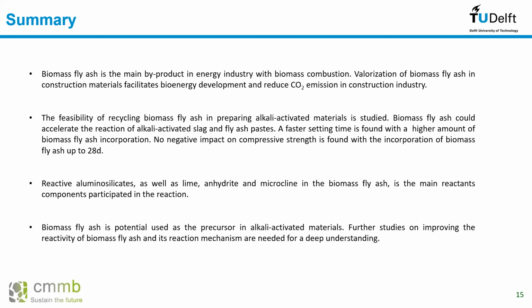Here we find that biomass fly ash could accelerate the reaction, and we can get a shorter setting time with a higher dosage of biomass fly ash incorporation. But the biomass fly ash brings no negative impact on the compressive strength up to 28 days, which is very good. And the reactive aluminosilicates, lime, anhydrite, and microcline in the biomass fly ash are the main reactant components participating in the reaction.